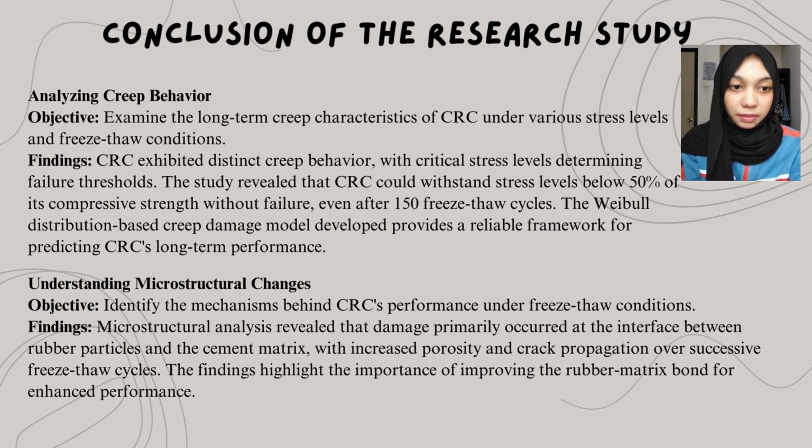Understanding microstructural change. Identify the mechanism behind CRC performance under freeze-thaw conditions. Microstructural analysis revealed that damage primarily occurs at the interface between rubber particles and the cement matrix, with increased porosity and crack propagation over successive freeze-thaw cycles. The findings highlight the importance of improving the rubber-matrix bond and its performance.